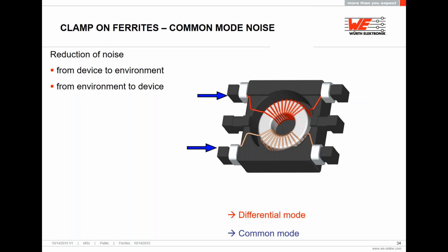So now, if we talk about common mode noise, common mode signals, we need to understand that both signals are flowing in the same direction, just as we can see in the blue arrows from this image. The common mode noise will create a magnetic flux inside the core that are in the same direction as shown here by the blue arrows. So the core will react to that frequency and convert it into heat. This is represented by the mushroom cloud in the middle of the core. This fact makes it important that you choose the right core for the specific frequency that you're working with.